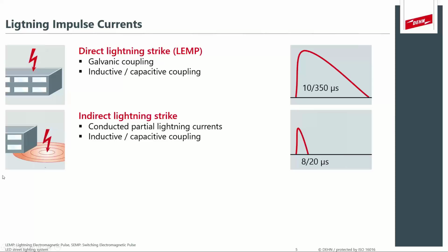Lightning can actually also strike in the vicinity of 500 meters around your building, or even 2 kilometers away from your overhead lines or power lines, and that lightning strike that terminates onto ground level then causes a mutual inductance or an induced effect over the lines of the structure 500 meters to 2 kilometers away.